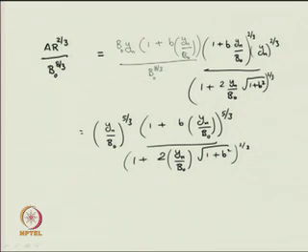So, for a trapezoidal channel, you are getting your non-dimensional section factor in the following form. Here you can easily see that the right hand side has the non-dimensional term y n by b naught at several locations.